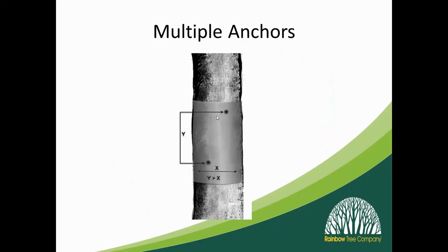And if you have them too close, it's just going to connect. So that's why they say to space them out the diameter of the wood, so you're still having the strength of the wood there. And then offsetting them also, not having them parallel, so it's not pulling the same direction.